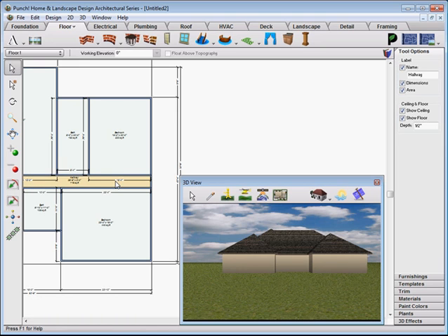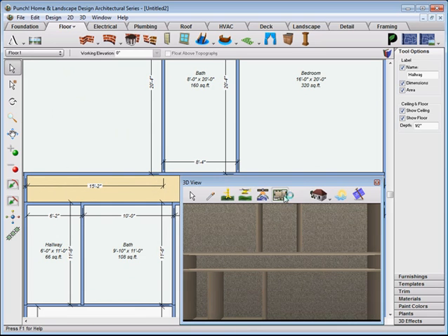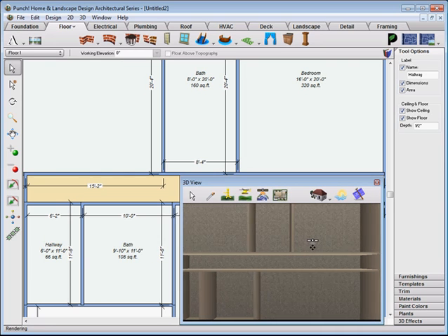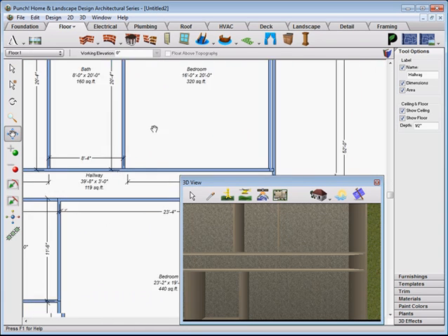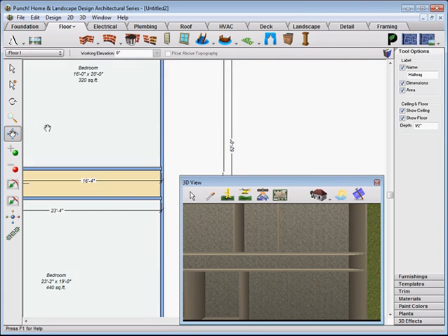To make it easy to look down into a room, in the 2D plan, just click with the left mouse button to select the room, and from our navigation tools, choose Room View. This creates a top-down view in 3D looking at the selected room.